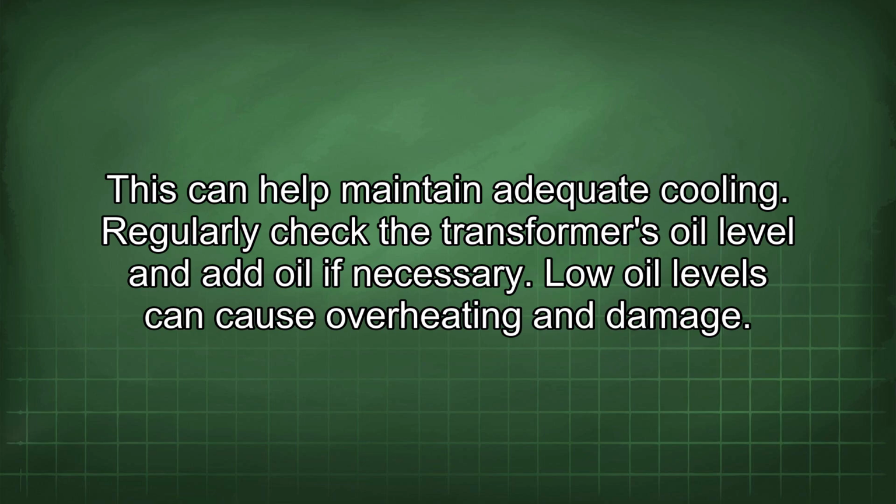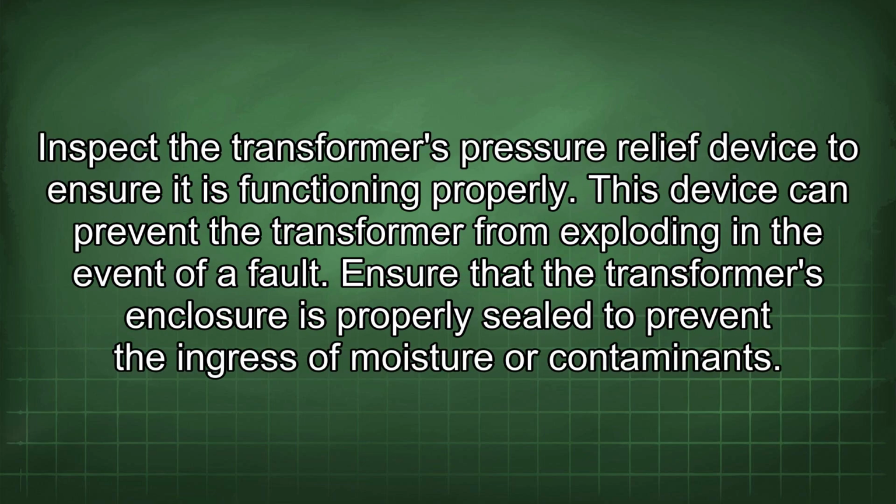Regularly check the transformer's oil level and add oil if necessary. Low oil levels can cause overheating and damage. Inspect the transformer's pressure relief device to ensure it is functioning properly. This device can prevent the transformer from exploding in the event of a fault.